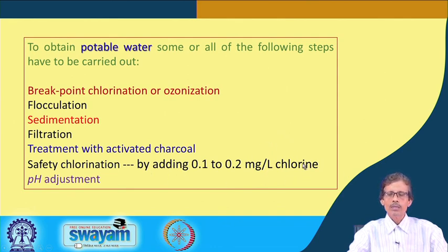The chlorine can react with the hydroxide ions, if it is slightly alkaline, to give hypochlorites or other active material based on chlorine. So, we should have a very low concentration of chlorine which can only kill the germs, the organic matter, the dye molecules or some unwanted material still present in water.